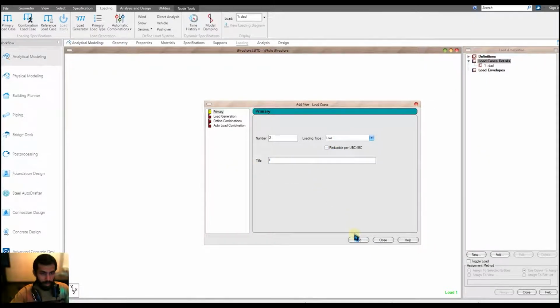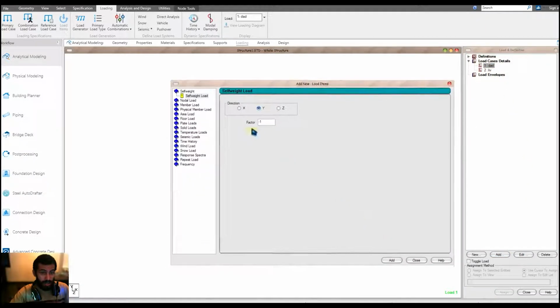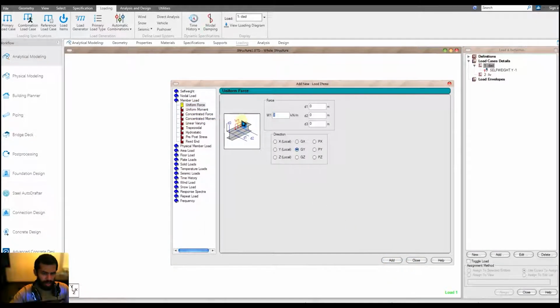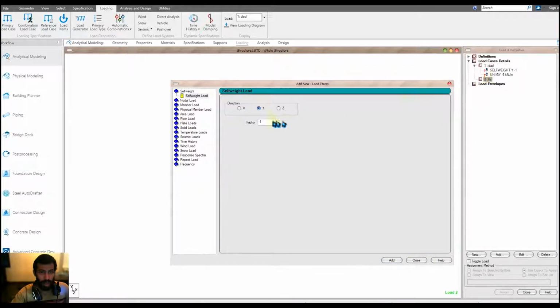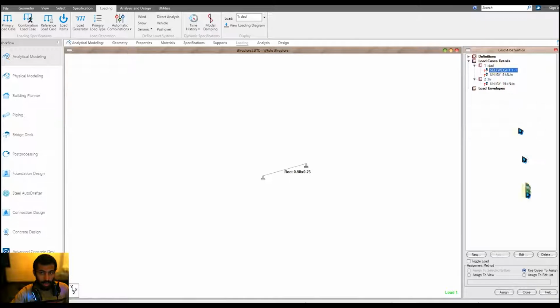So live is here. Okay, the first case in dead load is the self weight of the structure, which is added right now, and then the next load comes to be -5. I think the 5 is applied across the beam, so we don't want to enter any parameters here. Alright, now let's get into the live load. The load value is -19. Alright, then let's assign everything to view as if there is only a single structure here, and assign to view.